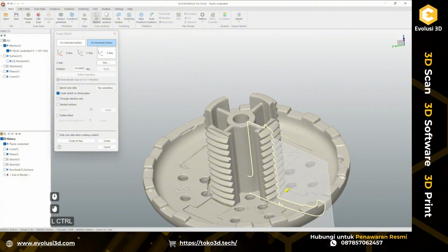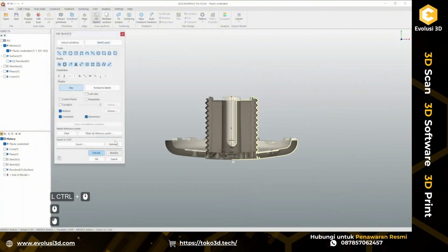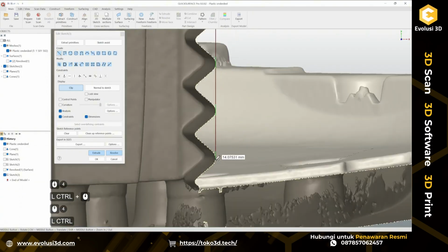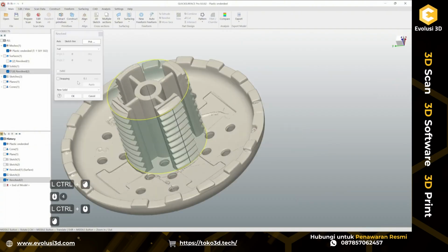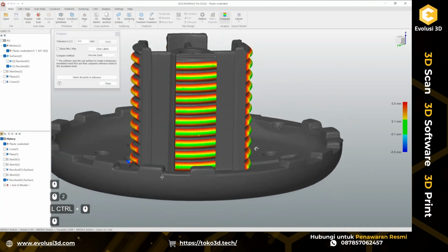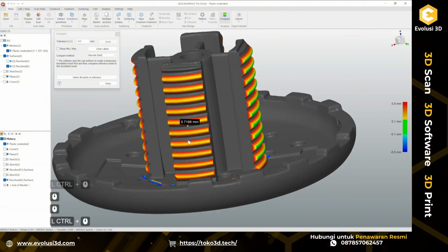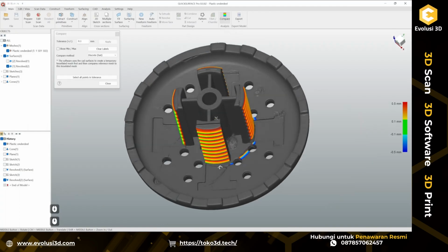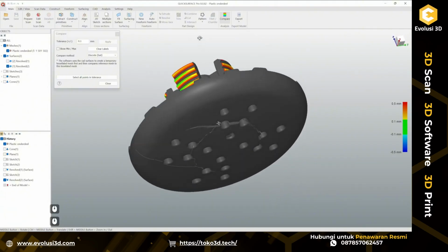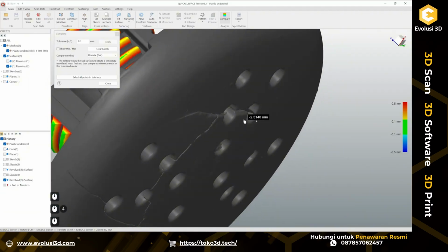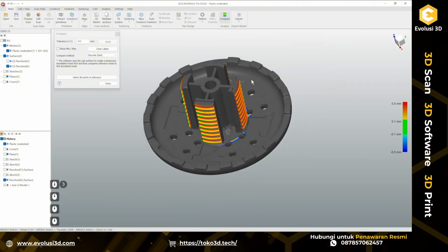Let's go to this one. Let's create another sketch here. And in absolutely the same way I'm fitting another entity here. Let's revolve it, and let's compare. So we're good here, we're good here, we're slightly off on this one, and we are half good here. So this means basically these two features are slightly twisted, and we can actually see here we have the biggest deviation between two surfaces. So this might make sense actually.